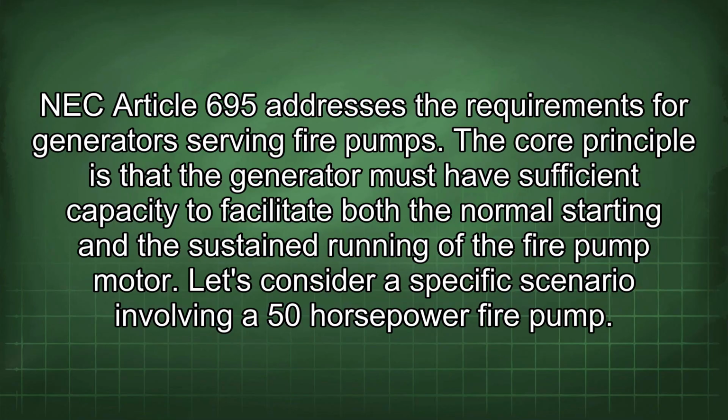NEC Article 695 addresses the requirements for generators serving fire pumps. The core principle is that the generator must have sufficient capacity to facilitate both the normal starting and the sustained running of the fire pump motor.